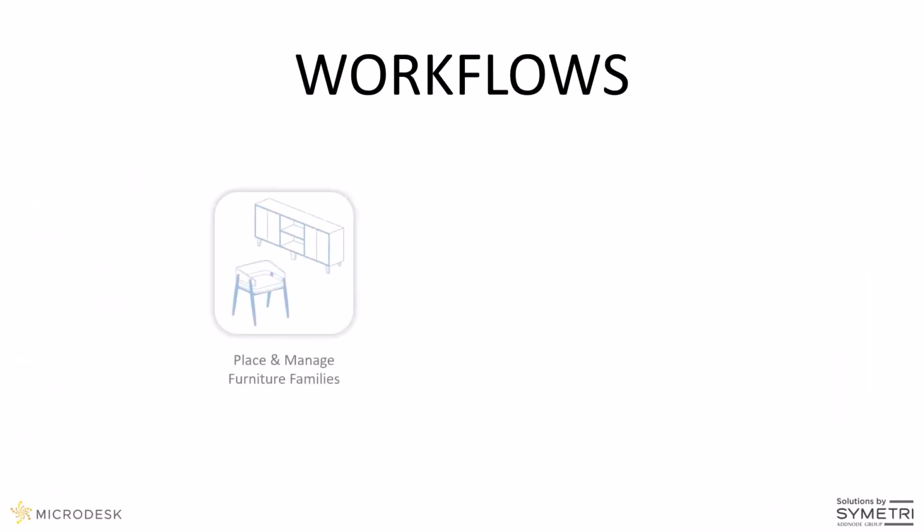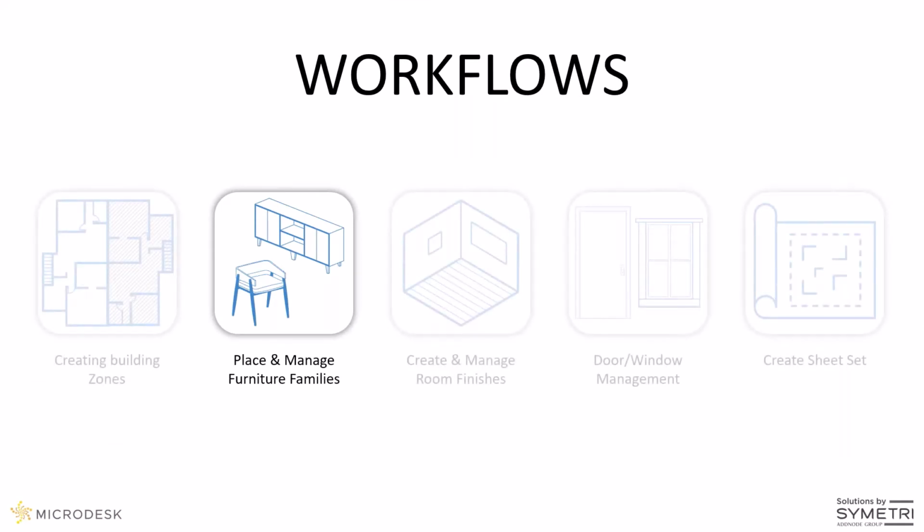And that brings us to our next workflow, which is adding those furniture elements to start that design process, right? Now I can add furniture elements to add to the designs of those different rooms. One issue that we always have with adding furniture elements from maybe our company's library is finding that library. With out-of-the-box Revit, I have to locate that location every single time. And for each family I want to place, I have to run the command independently. And this can be really cumbersome.